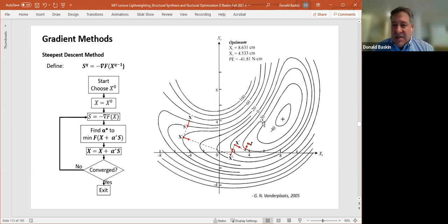And so this is a design space of X1 and X2. It's more complicated than some of the stuff I've shown you before. And so you start your optimization problem by choosing a location within the design space. In this case, we've chosen this X0 right over here. The procedure is to calculate the gradient of this objective function f at this point, which is facing this direction, and then choose a search direction, which is the opposite of that gradient, and then pick some step length.